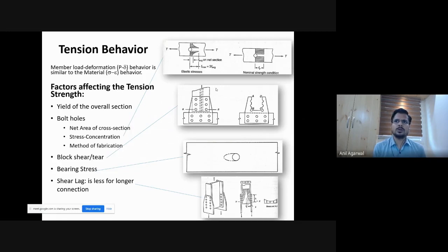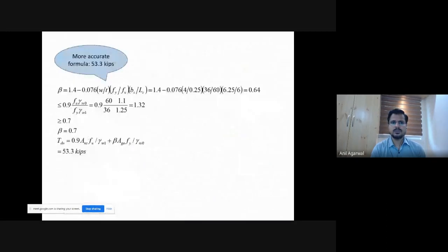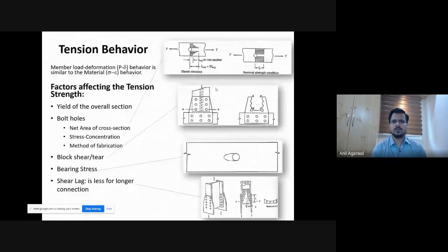Overall deformation of the structure, and as a result, deformation of individual members, is not that significant, and that's where the serviceability limits are generally satisfied. So for members in tension, serviceability limits generally do not have a very significant effect. There are some limits on the overall slenderness of the member, and I think I have a slide at the end for that. Yeah, this slide. We'll talk about it. As long as you meet those slenderness limits, you are generally okay.